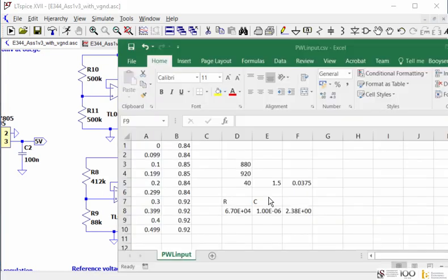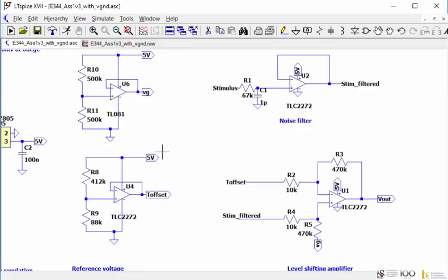I chose the RC filter cutoff frequency to be equal to 2.38 hertz. So that's quite low. And what you had to do now is to ensure that the 50 hertz noise is reduced substantially so that the output level is less than or equal to 80 millivolts. That's the one part of it. However, the competing part of it is that your rise time must be quick. So you can think of this as from two perspectives.